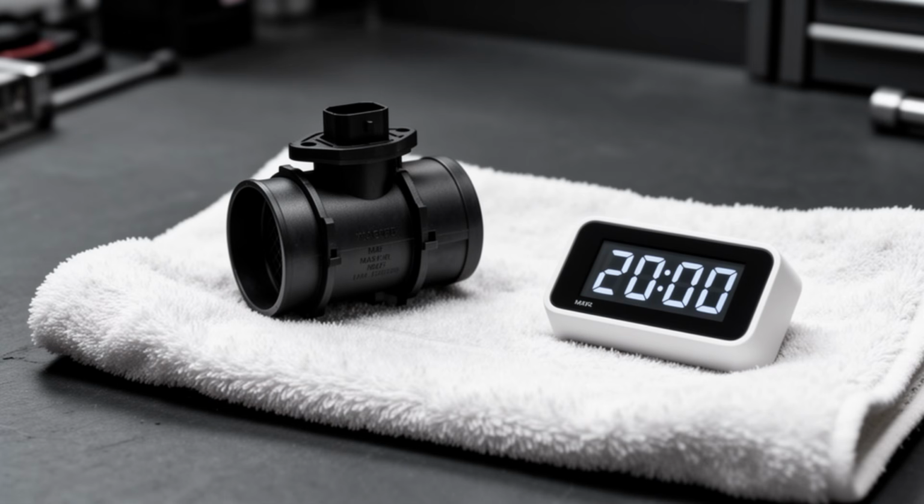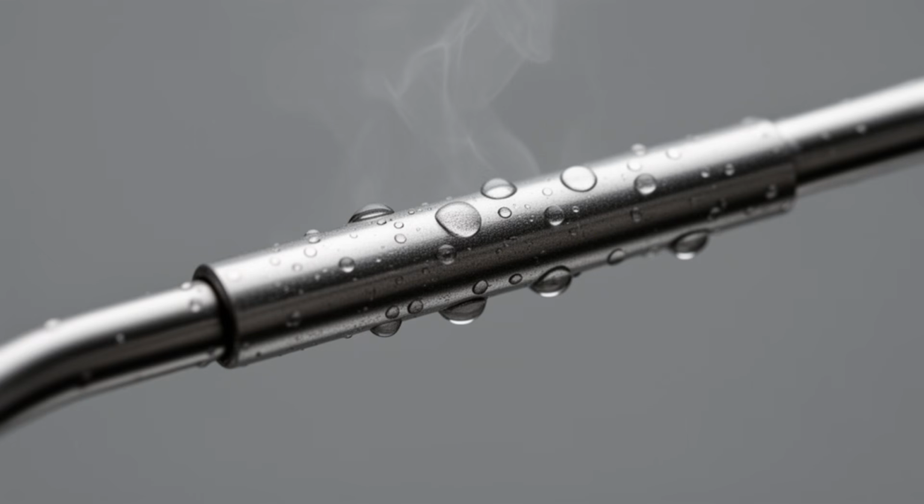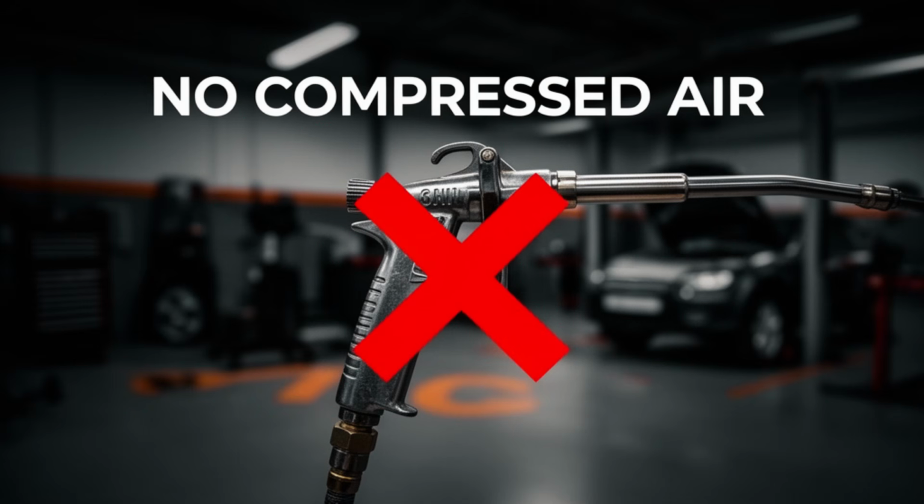Allow the sensor to air dry completely in a clean, dust-free location for a minimum of 20 minutes. The solvent is fast evaporating, but residual moisture in the sensor housing can cause an erratic signal if the sensor is reinstalled before full evaporation. 20 minutes at ambient temperature is sufficient. Do not use compressed air to accelerate drying. It risks recontaminating the element.